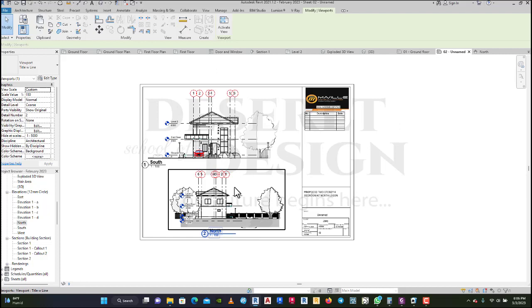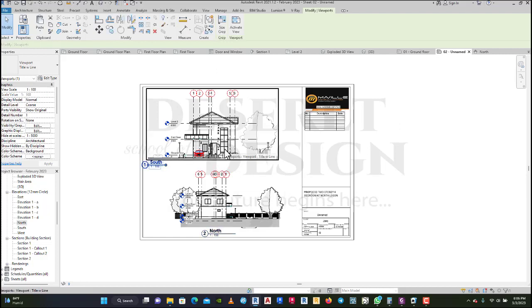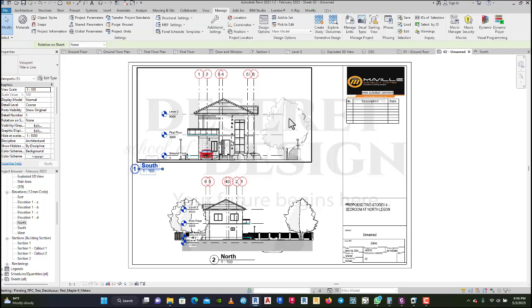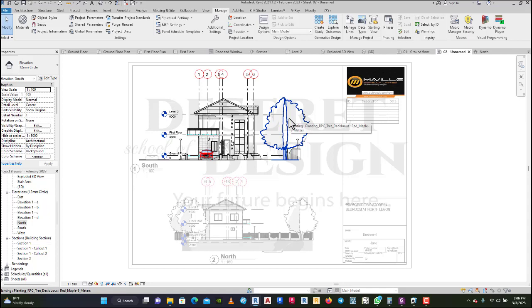Now you can be here and also open it up and work on the scale. Because if I select this, it's like you've taken your ground floor and put it here. If I want to change this scale also, it doesn't mean I need to go to my south view, open it and put it there. What you can do is open the south view from here. To open the south view, you double click inside. Now it has opened like that for you.